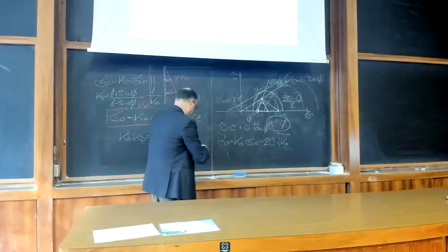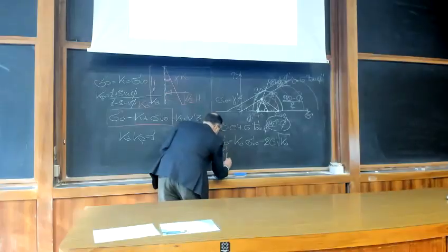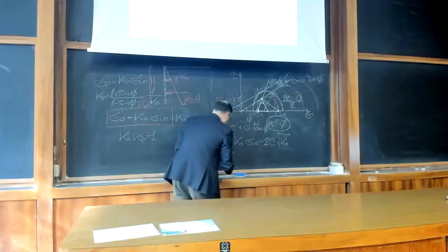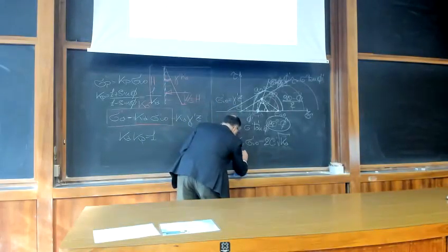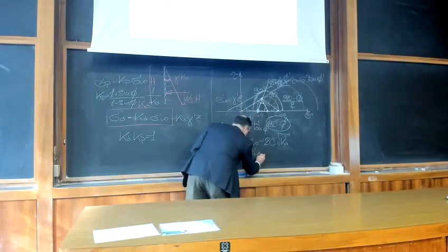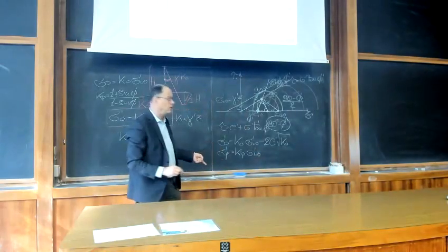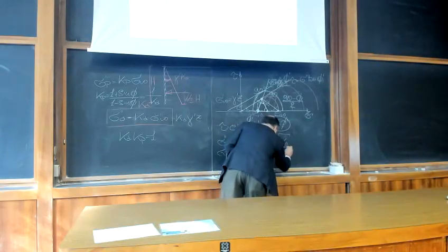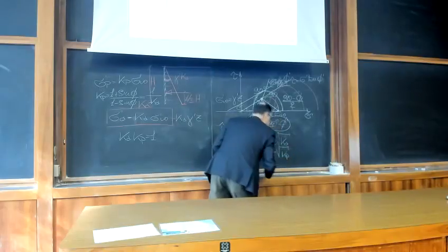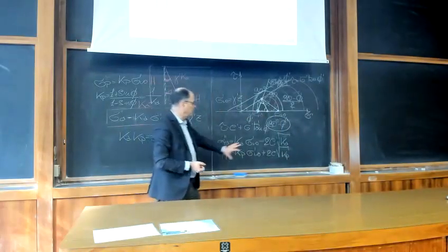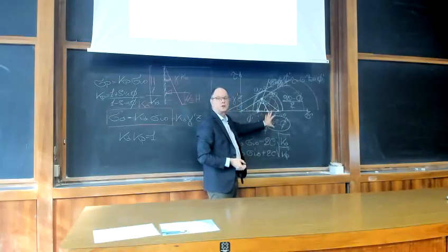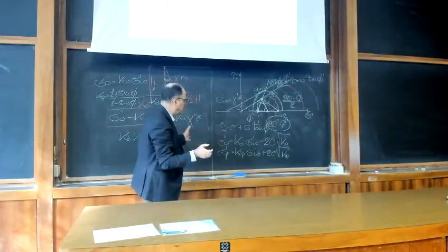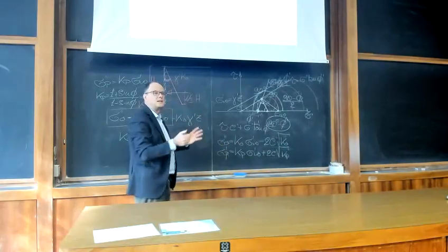And if you want to write sigma passive, the passive horizontal stress, you will write Kp sigma v naught, and this is the expression for a cohesionless soil. And in this case, you have to add 2c prime the square root of Kp. So you have an additional term if you have a soil with cohesion. Everything we have seen stays exactly the same.